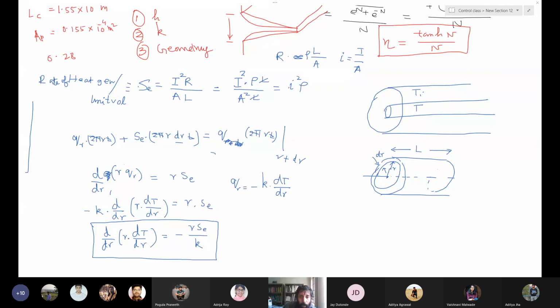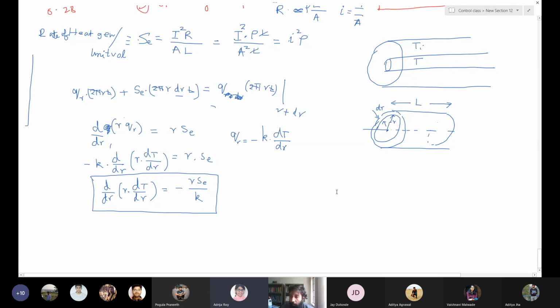So are you able to see the screen here? Yes, sir. Okay. See these two fins, say this is one fin, this is another fin. And beyond the boundary layer, temperature is T ambient. And this is how the boundary layer thickness grows. These are the two adjacent fins. So here it is T ambient, provided this gap is greater than twice the thickness of boundary layer. You agree to that? Yes, sir. I got it.